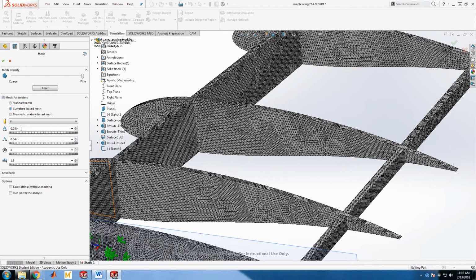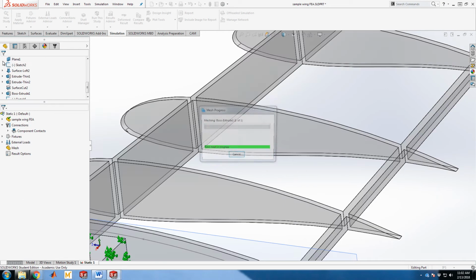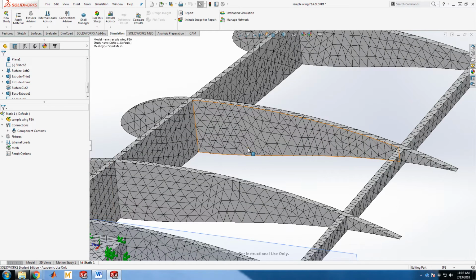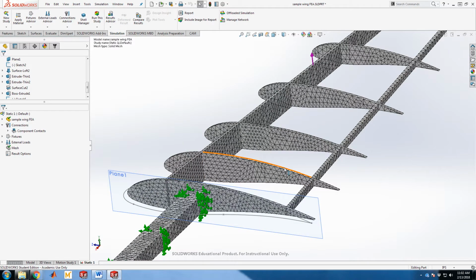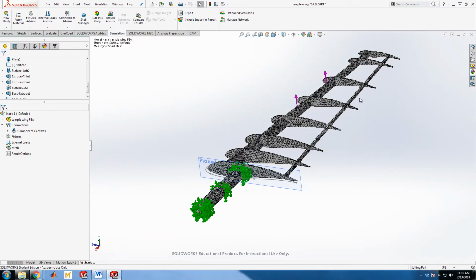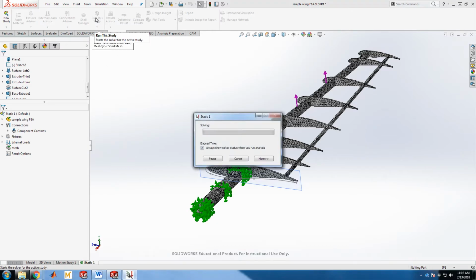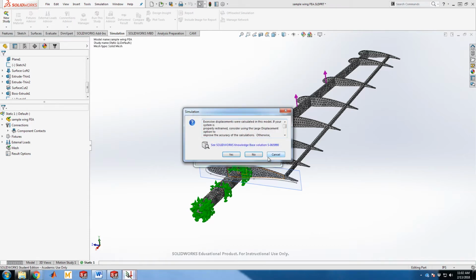We'll create a simpler mesh, go back down to 0.2. That should be much quicker to solve. But also you see the resolution is just smaller. So that's the decision you have, and that certainly does affect the quality of your final solution. So now we can run the study given the boundary conditions, the loads, the mesh we have. This is actually going through the process of solving.